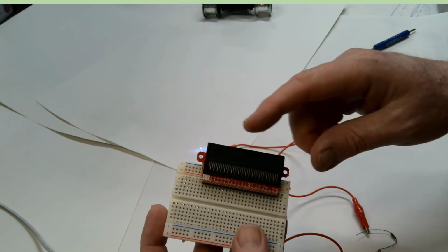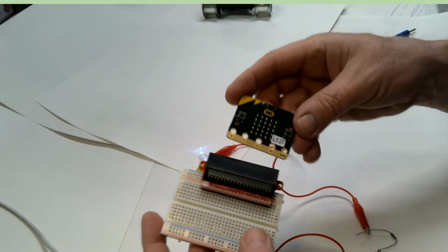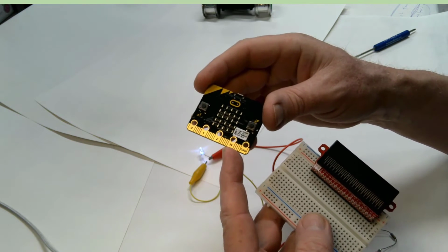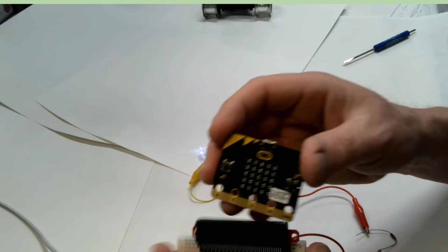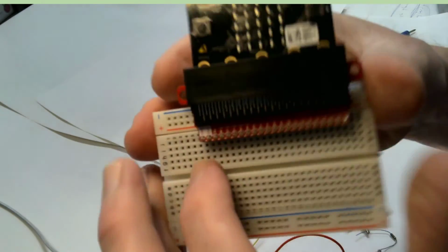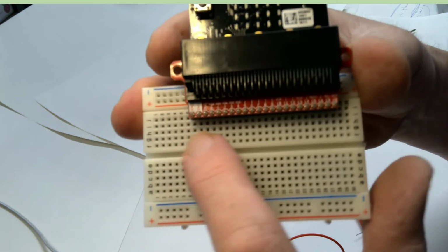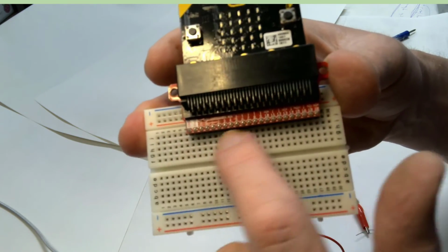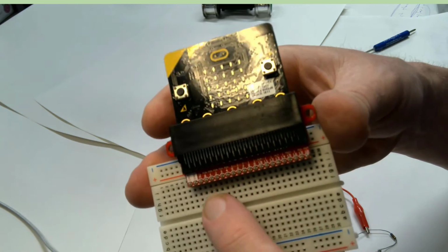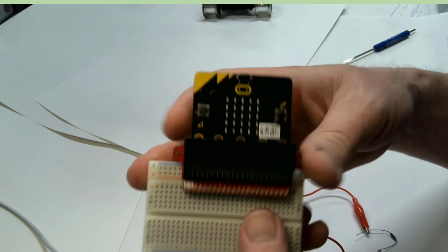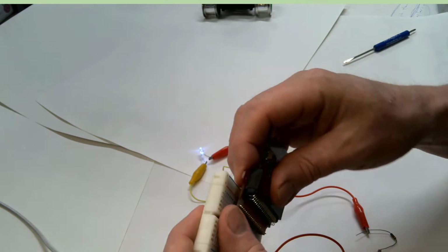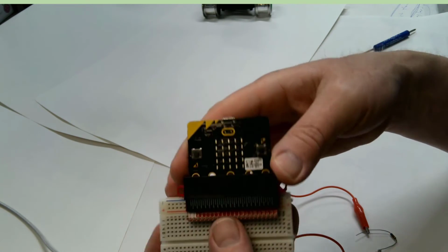This is called a breakout board, and it's extremely handy for connecting devices to the pins on our micro:bit, because these little edge connectors are a little bit difficult to connect to. But if I plug this into the breakout board, I can now plug pins into the same set of holes that these pins are plugged into right here. So that'll make it really easy to hook up circuits and things to our micro:bit. And then later we'll pull this out of the breadboard, and we'll just connect wires and plug them onto the pins that I currently have plugged into the breadboard there.